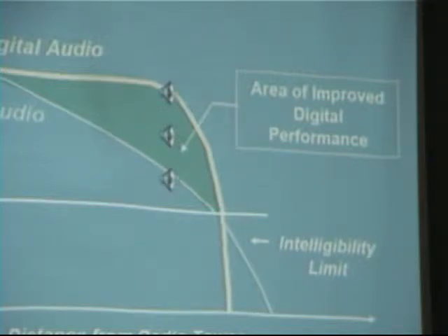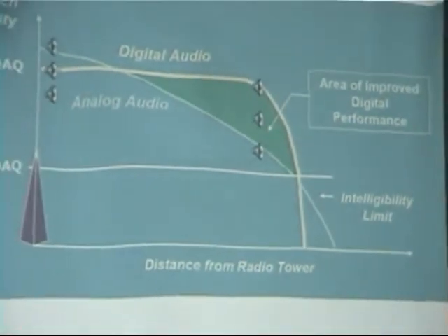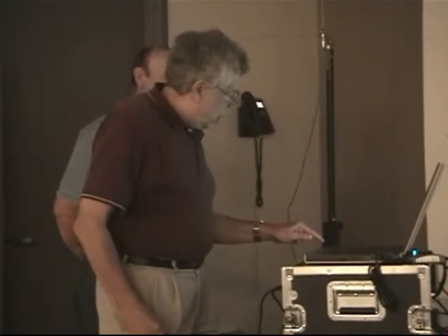Now, if we went down to where we had to open the squelch and we could just hear a little bit of audio, the digital radio would be gone, and you might be able to pick up a little something with the squelch open. For the average user with the squelch set, this is what happens to you in a weak signal area.